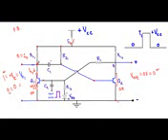As the voltage between this terminal and this terminal is 0, the voltage between this terminal and this terminal will be equal to 0 as long as the input pulse is applied. That means the transistor Q2 will not be in on state, because it will not get sufficient voltage to drive the base to emitter junction in forward bias. Therefore it will now turn off.